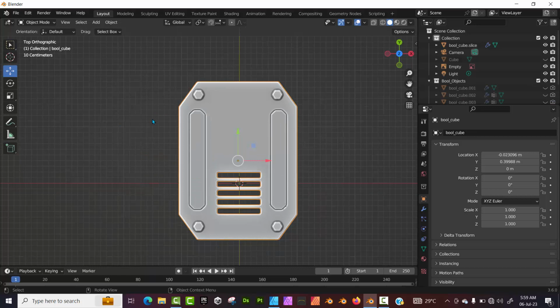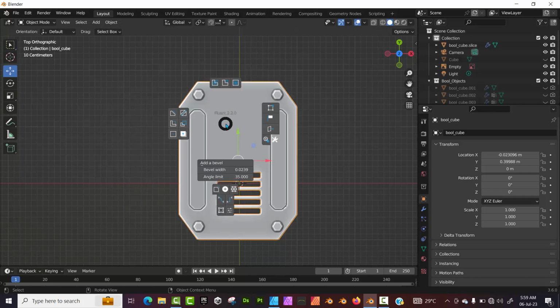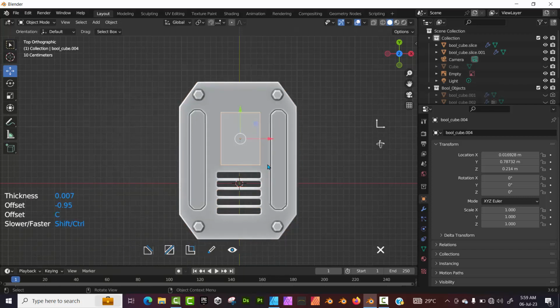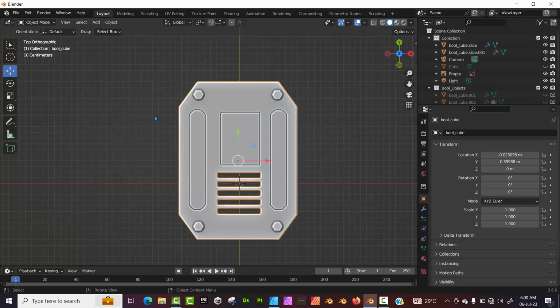And let's right click and leave that, and let's add another slice right here like so. So click on the object, press F, let's go to slice, and let's just create a nice slice like so. Let's drag in a little bit, just a little bit, to create that slicey shape, and I'll just leave this at so and right click to validate.